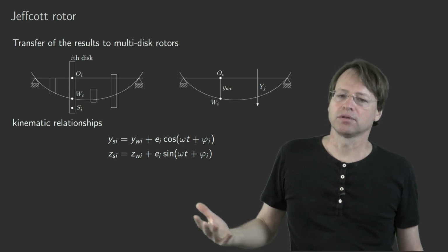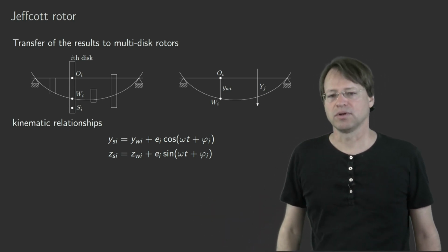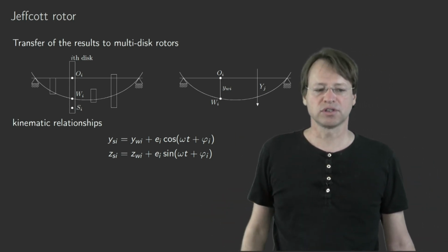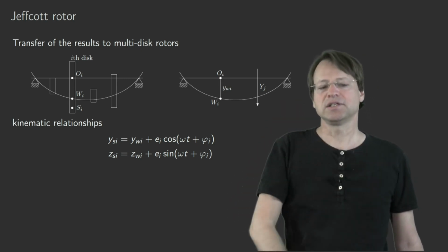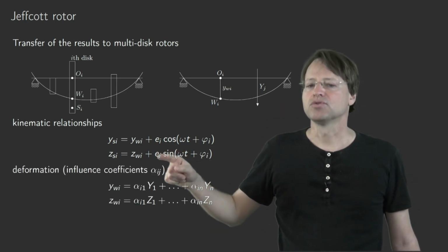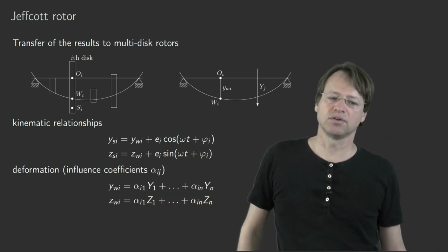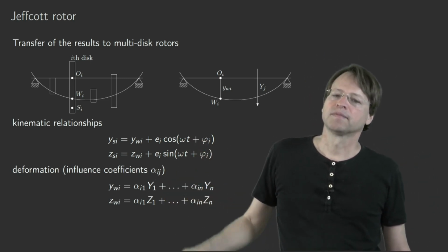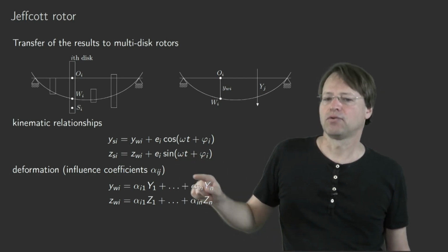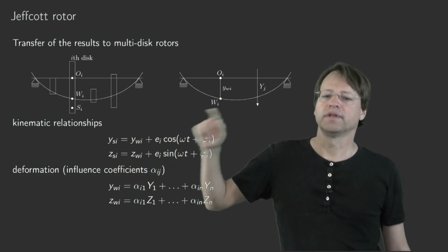This is called the concept of the influence coefficients. So you have to determine the influence coefficients by studying single load cases, and then you superpose these single load cases to study the influence. These are the influence coefficients here of each force on the displacement.